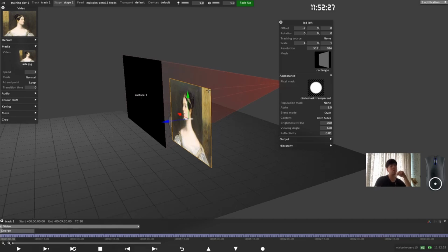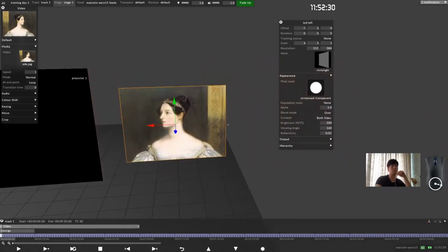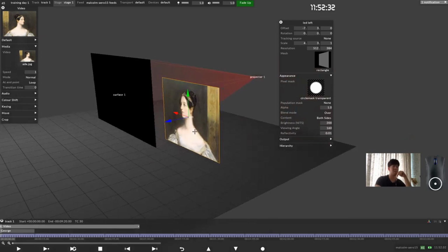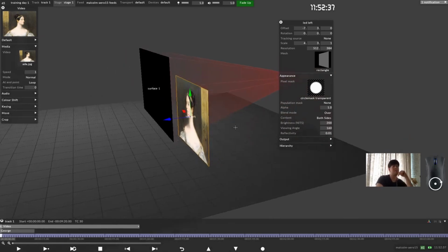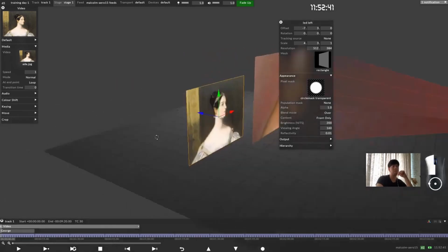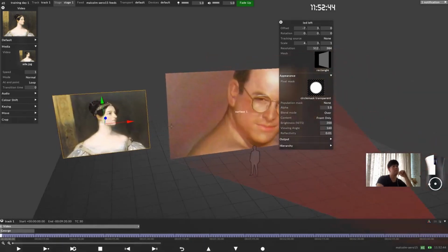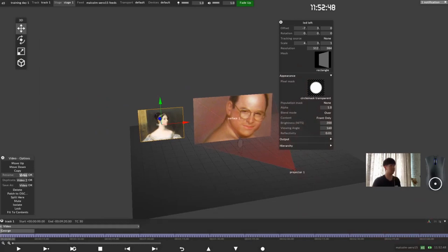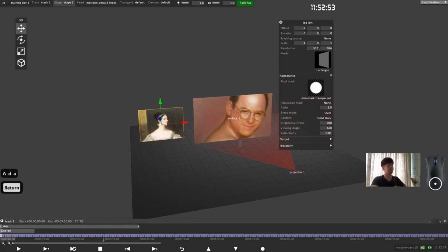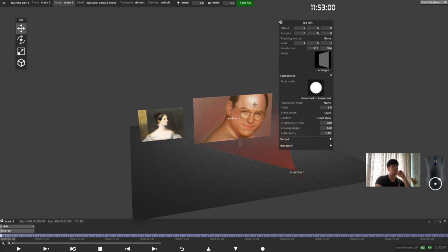I try to only show one side, because if you show two sides, it is also rendering in your GPU, I mean in your machine, which will take up performance. So on the content, I'll choose front only. This is always the front. Same thing, I like to rename my content. Then I'm going to scale down. Right now I have two contents on my screen.